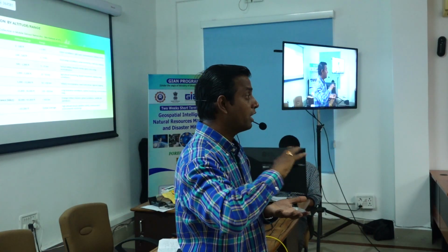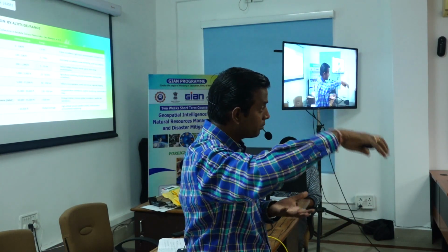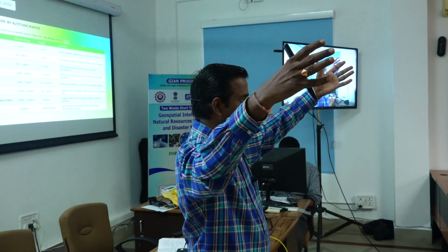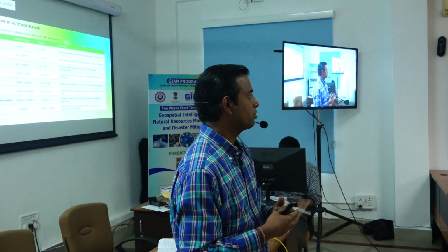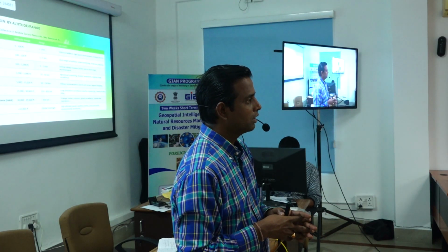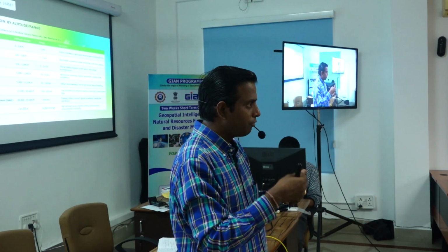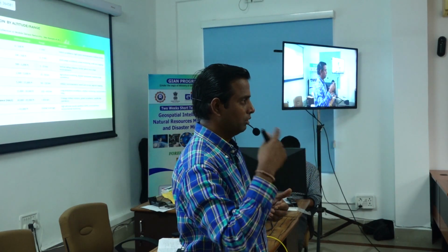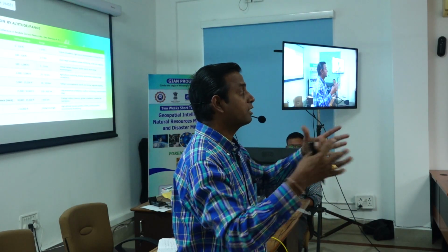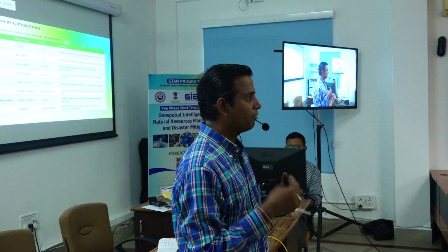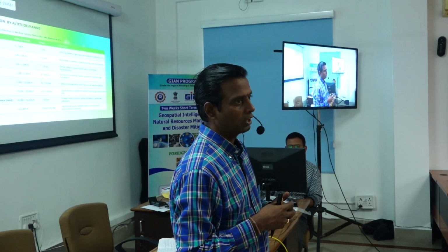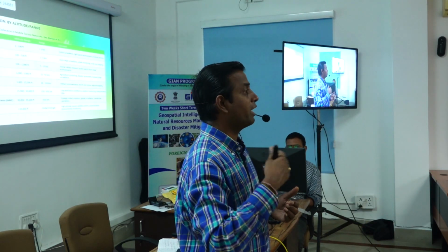If the survey area is higher, let us examine the same case for the UAV. First, let us say we survey EDC, then later we survey the complete IIT. So what will happen? In case of the UAV, the number of flying hours is more. In the UAV case, the number of flying hours should be more instead of increasing the manpower. Here, more flying hours means we should increase the battery capacity, otherwise a number of batteries are required.